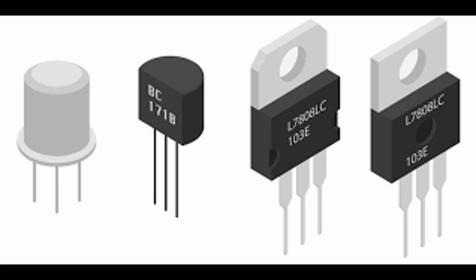Limitations. Complex structure. More complex than traditional thyristors, leading to higher manufacturing costs. Thermal management. Generates heat during operation, requiring effective cooling solutions. Gate drive requirements. Requires a specialized gate drive circuit capable of providing the necessary control signals.